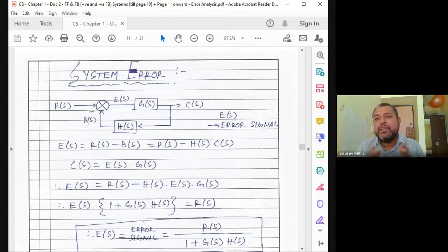You can write it down. The first signal, the base signal, is impulse, delta t. If we integrate delta t, we get unit step, that is u(t). If we integrate u(t), we get ramp, that is t u(t). And if we integrate ramp, we get t square u(t), or we call it t square by 2 u(t), which is a parabolic input. And we can come in reverse.